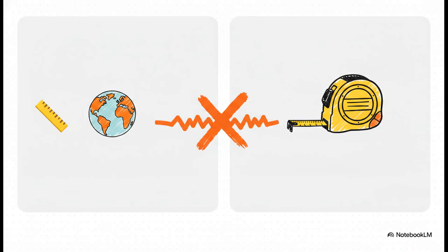Right off the bat, one of the first things you'll notice is that API 5L speaks 2 distinct mathematical languages: the International System of Units, or SI, and United States Customary Units, or USC. But here is the absolutely crucial point. While the spec uses both, you can never, ever combine them on the same inspection document or pipe marking sequence. If a purchaser specifies metric on their datasheet, everything has to be metric. It's a hard boundary, and it's there to prevent catastrophic measurement errors out in the field.